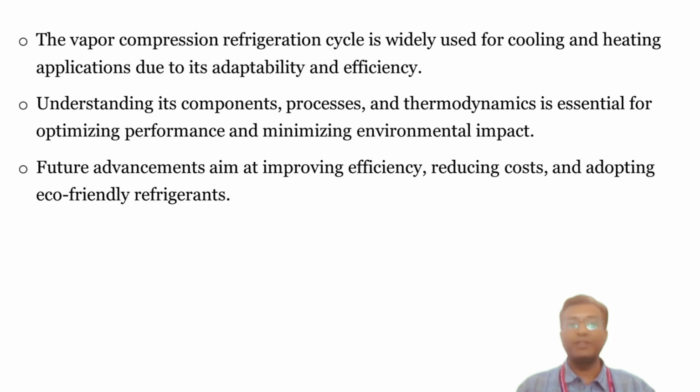For homework, sketch a TS diagram for the vapor compression refrigeration cycle and label each process. Try calculating the COP for a refrigerator absorbing 200 kilojoules of heat with 50 kilojoules of compressor work. These lectures have shown how the vapor compression refrigeration cycle blends science with practicality, shaping comfort and industry.